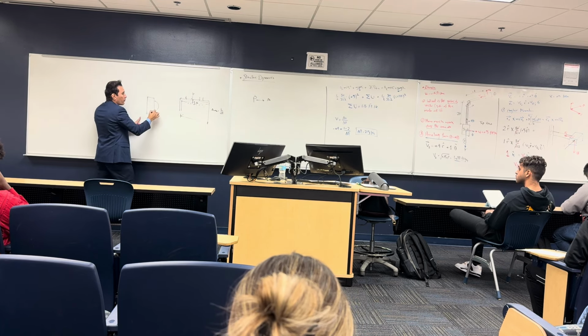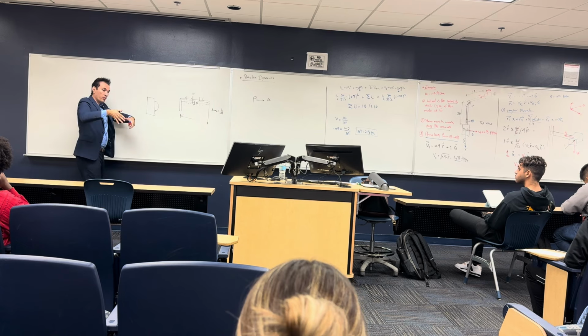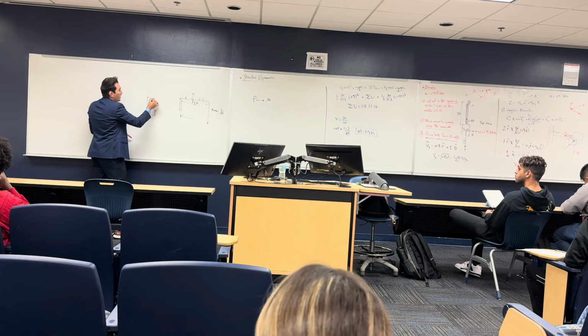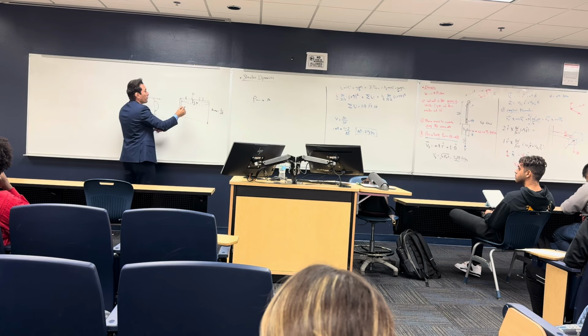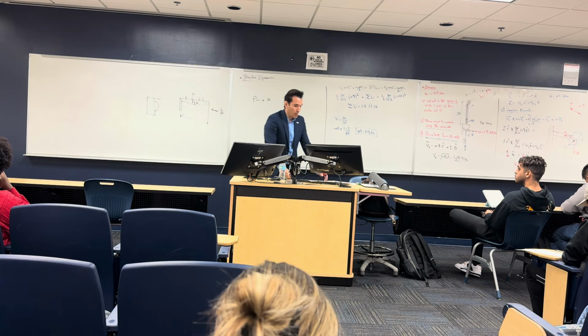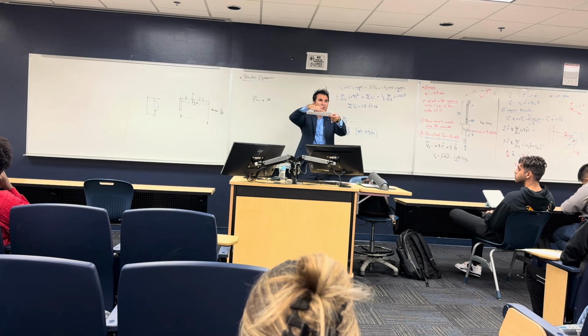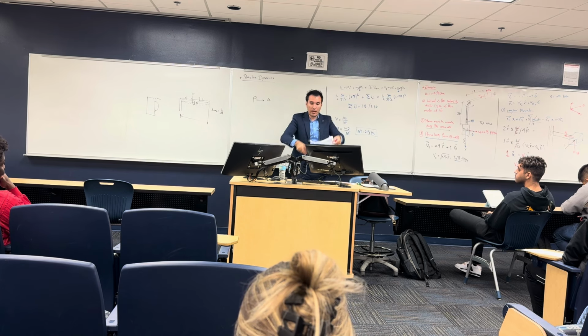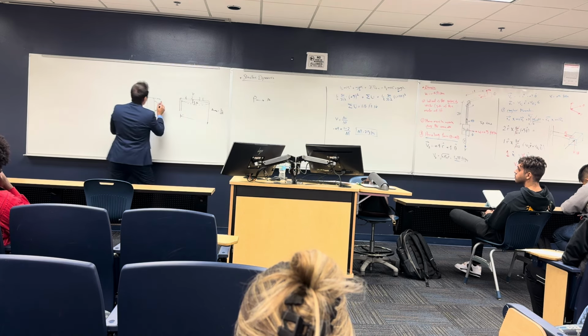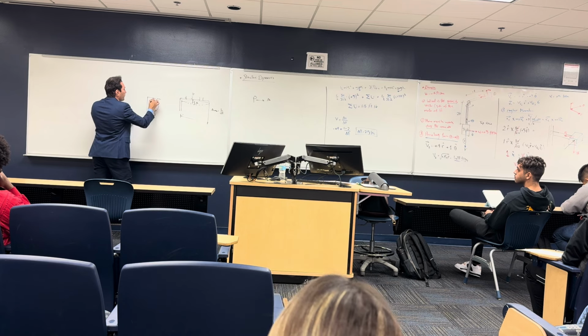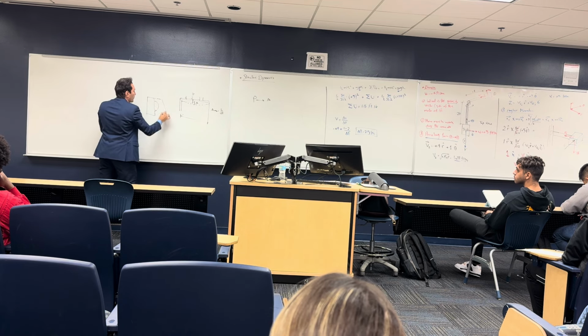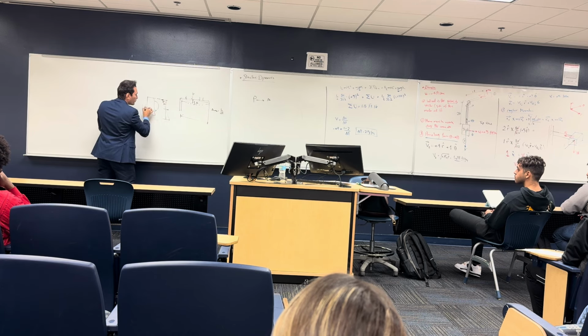It's going to have a bending moment. The section on the top is going to have compression or tension? Compression, and the bottom is going to have tension. So the cross section has compression here, compressed until it comes to a neutral axis, and then you have some tension.